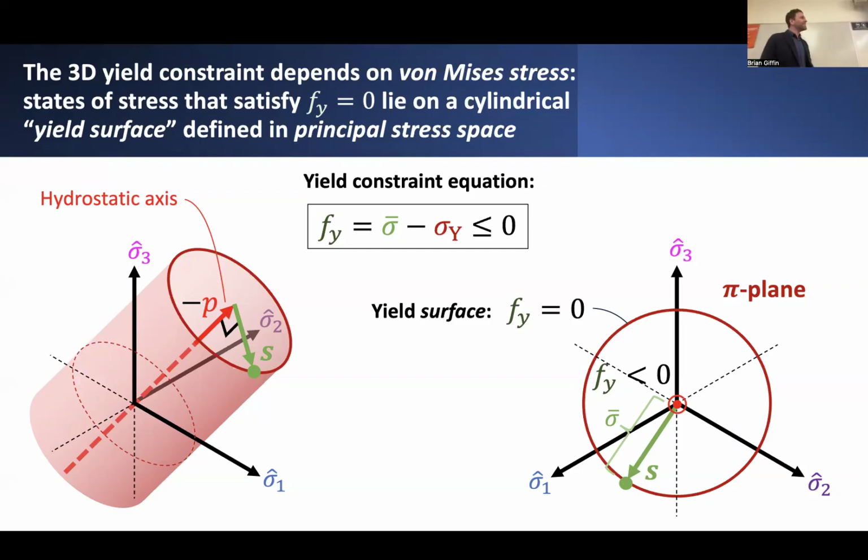They suppose there is some constraint imposed directly on the von Mises stress, such that the von Mises stress in some chunk of material being subjected to loads has to be less than or equal to some yield stress, the maximum stress in the material that can be sustained before plasticity starts to occur.